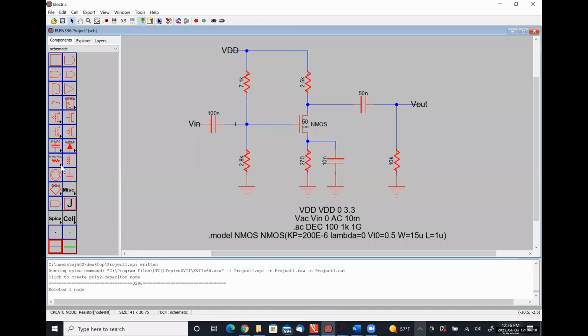If you mouse over the resistors, you have normal, so like a regular LTSpice resistor, or an N poly, etc. I made all of mine high-res poly because that's what these are supposed to represent. That should not matter, okay? For the MOSFET, you have multiple options here. The one that I chose is just this general one right here where it doesn't have a body connection because we don't really particularly care about it right now.